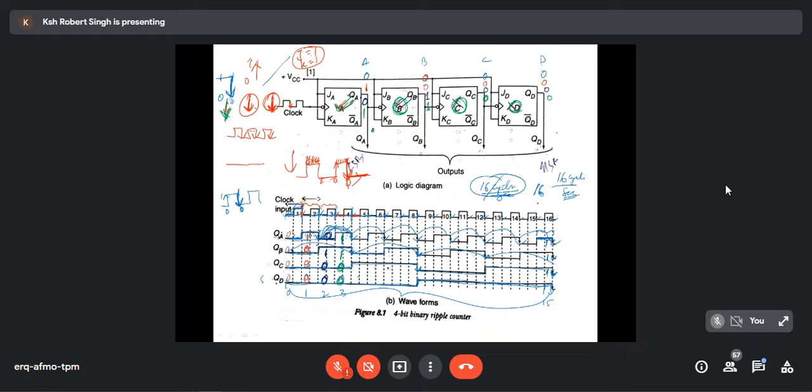Like that, you have to analyze, and the same thing will come. This is the real way of understanding how the circuit works. The transition, negative edge, as I say, it is a negative edge trigger. I never say it is a level trigger. I always say that if there is an arrow coming straight in, it is compulsory an edge trigger. But the bubble decides that it is a negative edge trigger. If there is no bubble, then it will be a positive edge trigger.